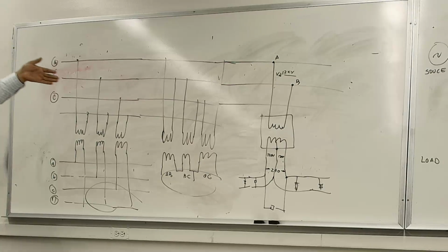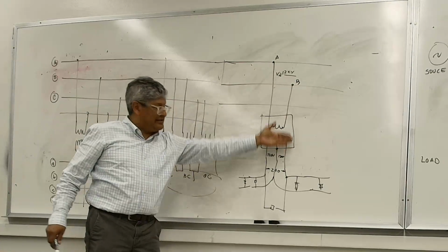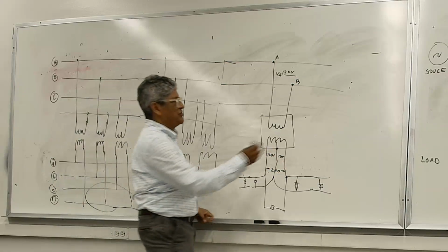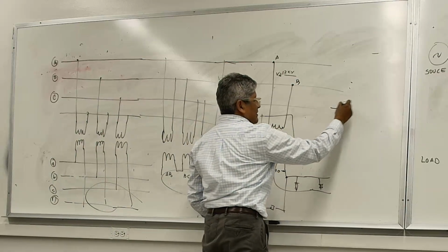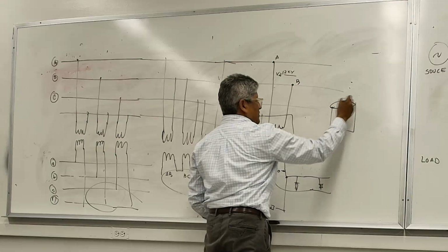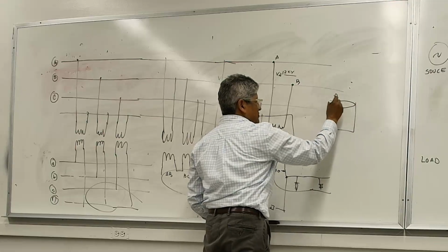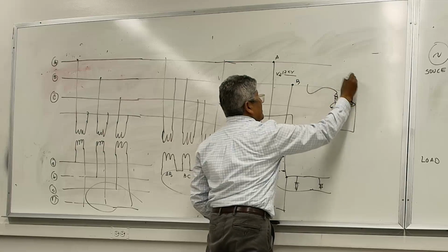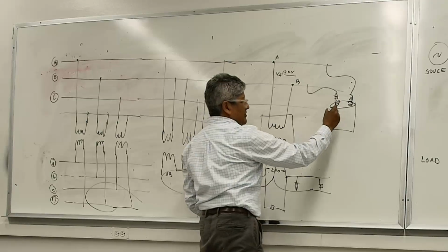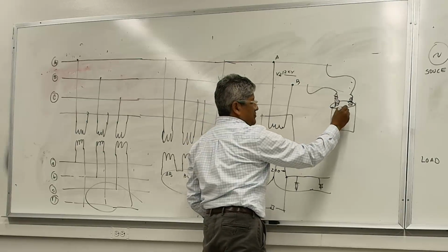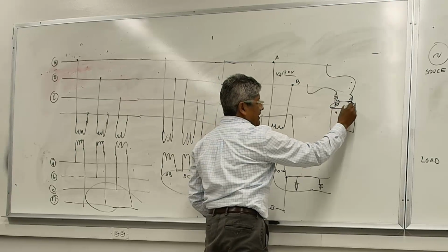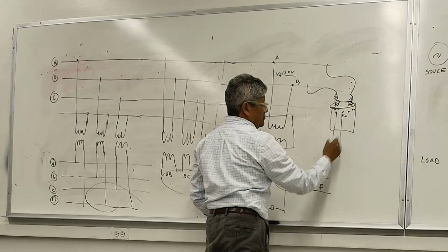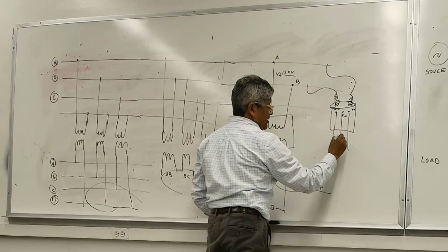Physically, as I said, this is a single phase transformer, and I think I gave you the picture. If you remember, we had a picture and it looked like this. You'll see it outside. Here's the insulator. Basically, that's what it was, connected to A and B. And then here, you'll see these things right here. This is called X0, X1, and X2. Between these two is 120, 120.